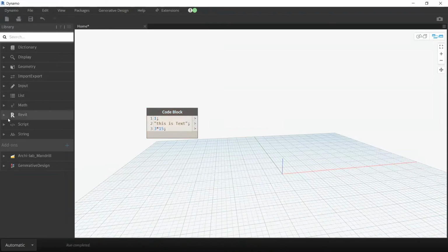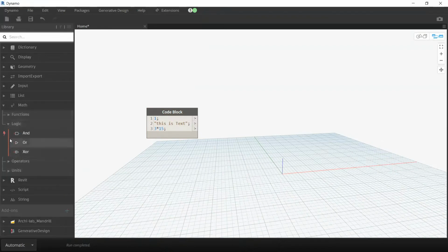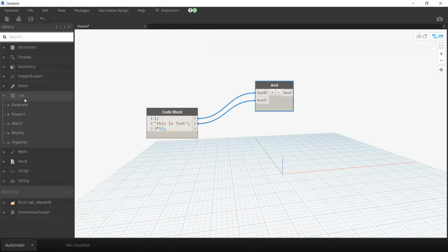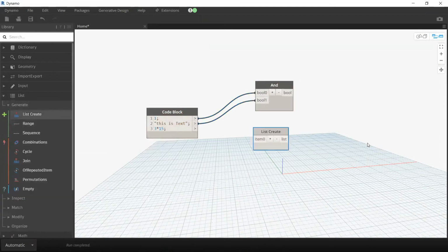Again, there's a lot of different inputs or even Revit math and things like that in here. So I can go through and use the scripts and basically just select that one and then take these inputs into that just by simply selecting and then putting them into the right path. And then getting a list or something, generating that list. And you can see how I can now take that into there.